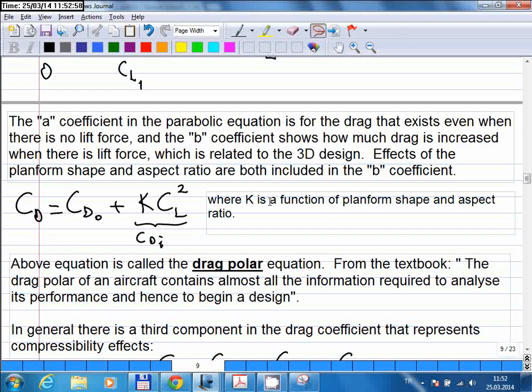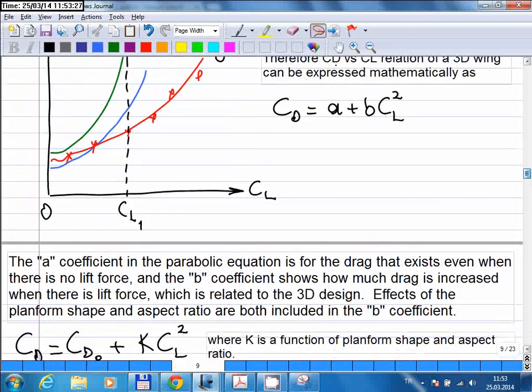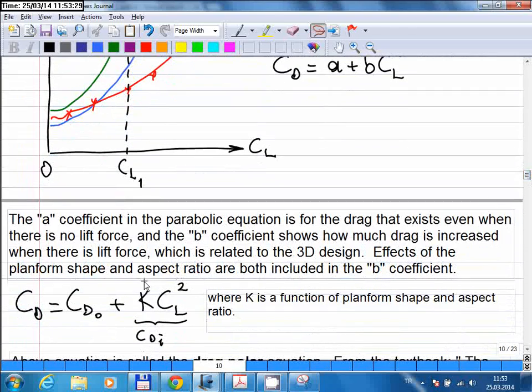That means you have to carry more fuel, and if you are carrying more fuel, then the amount of useful cargo you can carry will be reduced. And to be able to carry more cargo, you need to make everything larger. That means your engine needs to be even larger, so everything is related to each other. And to find the best performance in this circular argument is to find a way to make this K coefficient as small as possible.